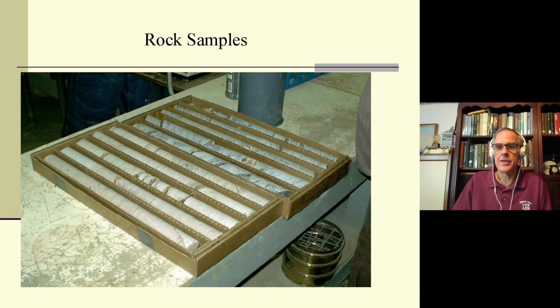And this is the first example of a sample, in this case, rock samples. And these are real rock samples from this area, which were taken using rock coring. Basically, the idea is that you core around the rock, usually using some type of diamond cutter, with the result that you get a nice cylindrical shaft of rock.